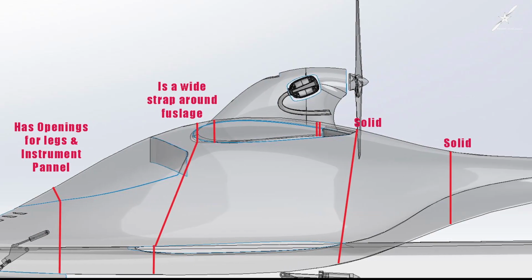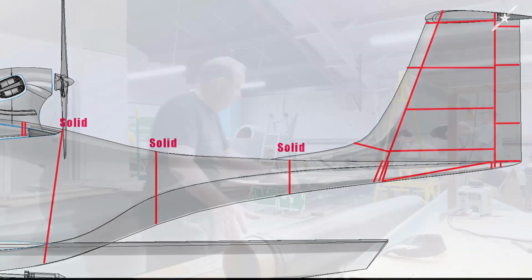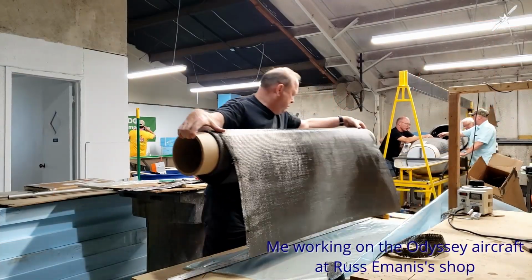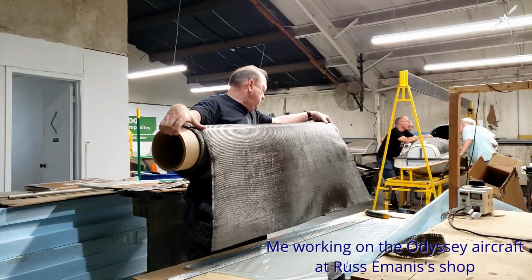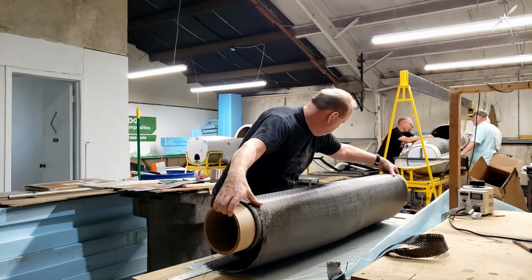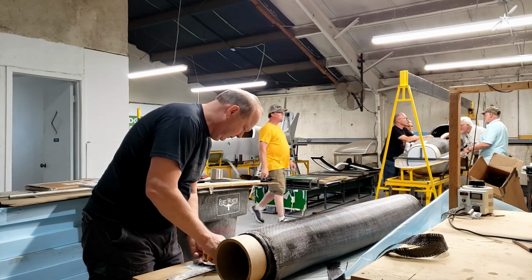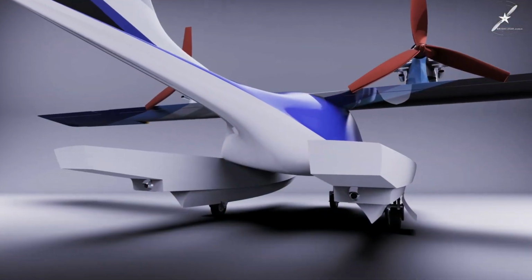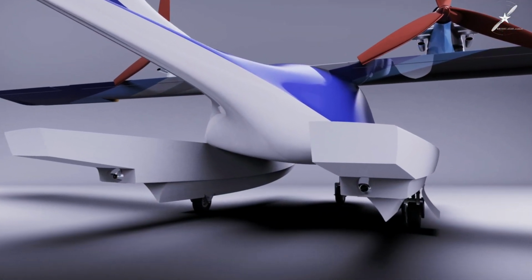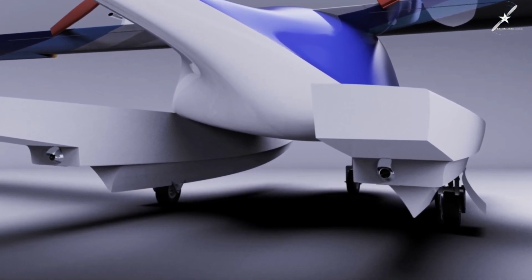Aircraft structures such as ribs, spars, end caps are all being input now. Almost all of the aircraft is made of composite materials, primarily carbon and fiberglass, but other more flexible composites will be used in areas like the pontoons to absorb impact. The bottom of the pontoons will have a removable stainless steel strip to protect it from sand, logs, rocks, and other debris.